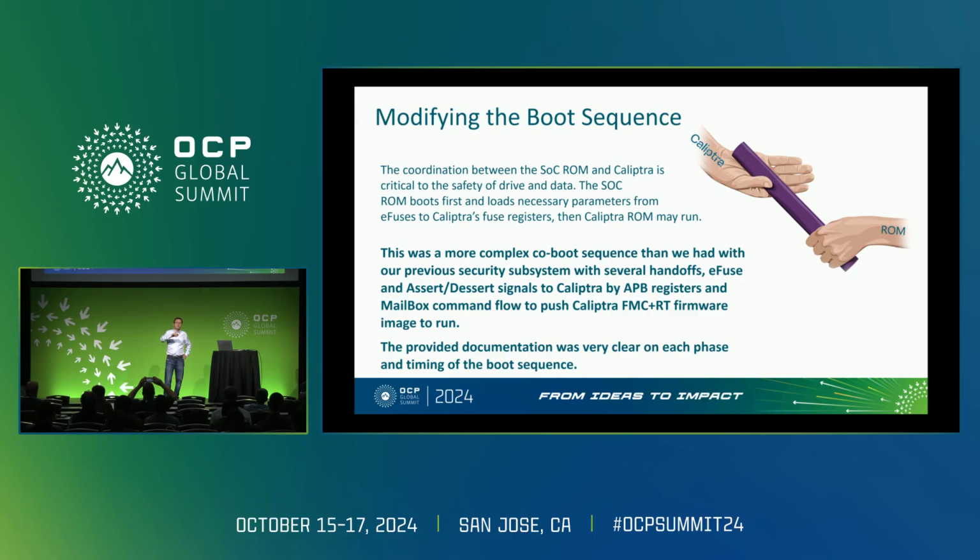And later, we could bring up our firmware code within a week. Only one glitch: in our RSA engine, we misconfigured it, so we saw the signature was not correct. We fixed that in the firmware, and so far we see a very seamless boot up sequence, starting from the Caliptra to our own full-blown firmware.